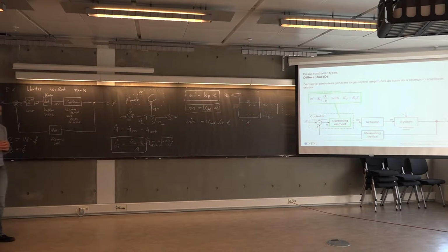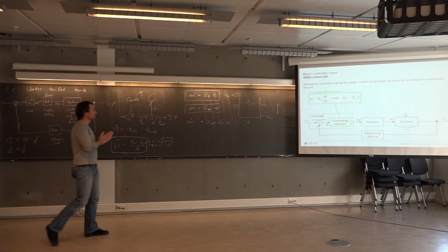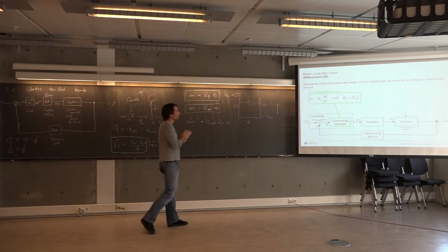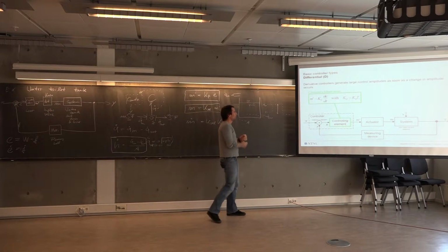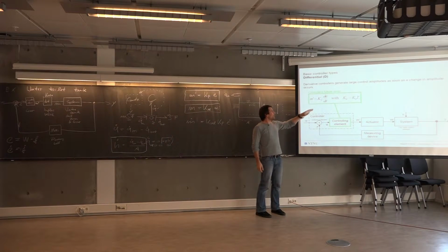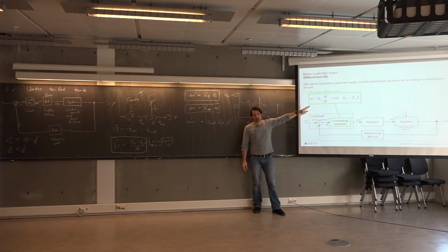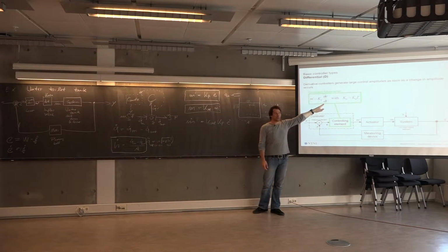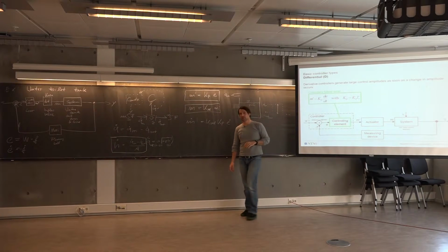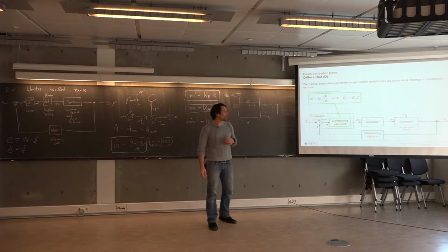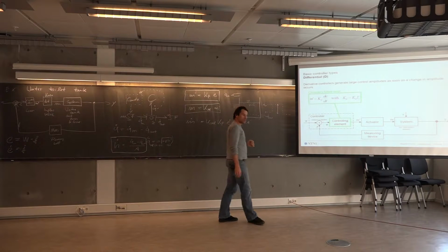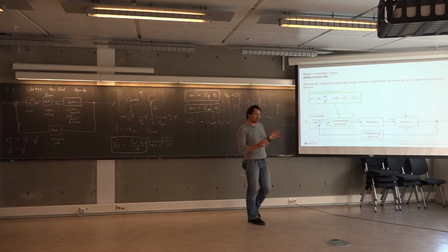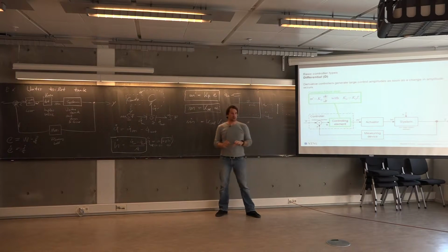Another type of control is derivative control. And again, we have some similar constitutive equation which relates the manipulated variable to, in this case, the derivative of the error, the rate of change of the error, which means that you try to estimate the future of the error, sort of, right?